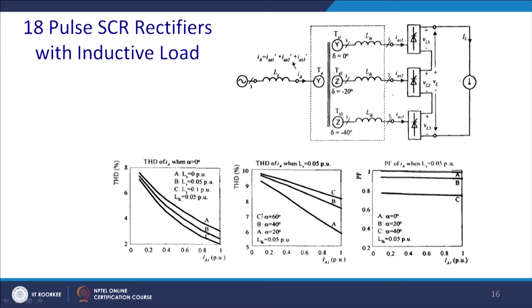So you have a constant current source due to the highly inductive load, and there is a source inductance. Generally you have to connect some amount of inductance before it, to smooth out the THD part of it. So it will generally make this more continuous.